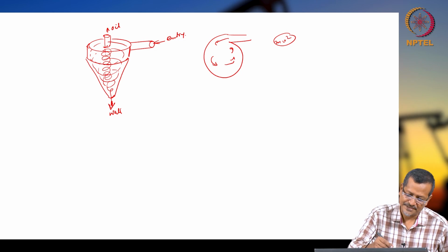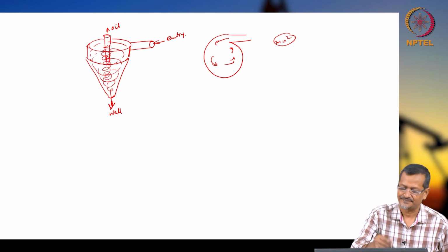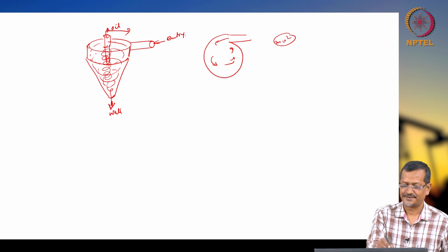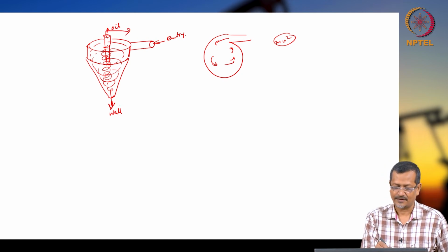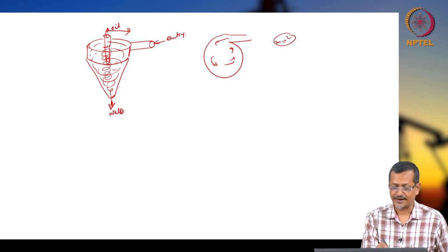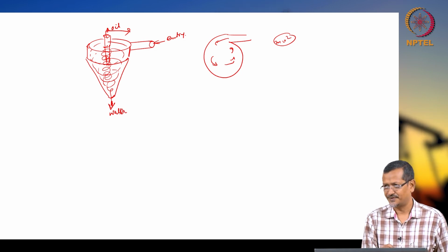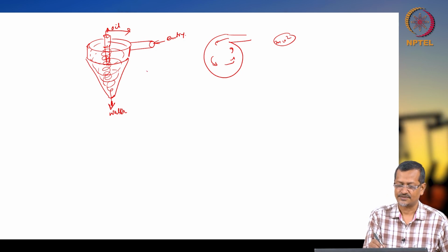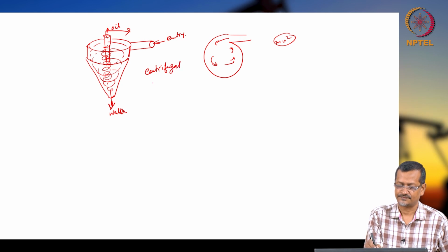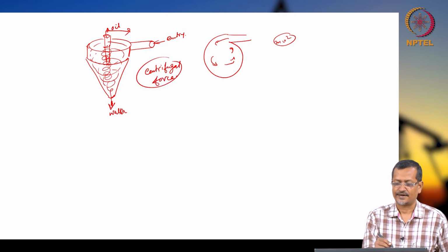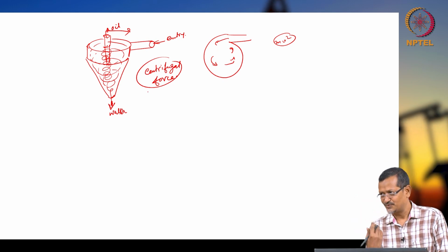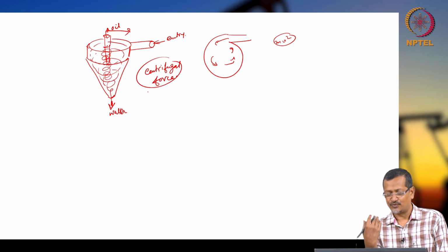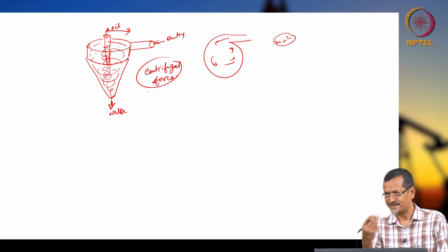Now, you put a long pipe from the top and suck the fluid. So, you get oil from the top, water from the bottom, and this is the entry. This works based on centrifugal force, and it is assisted by gravity, right? When it is rotating, it is going down also because of gravity. Which is going down? The high density fluid. If you have sand, sand also will go down.